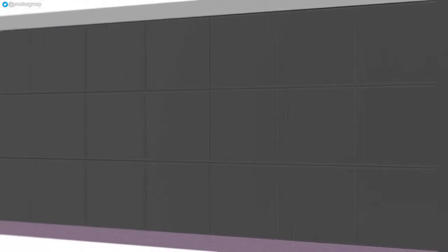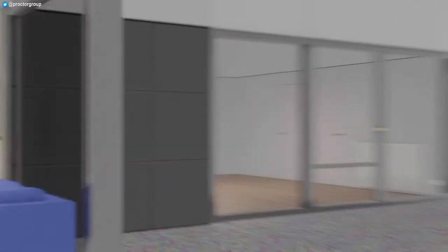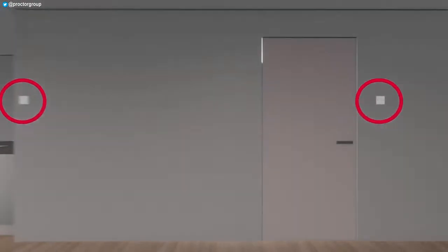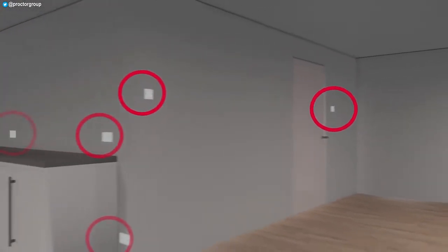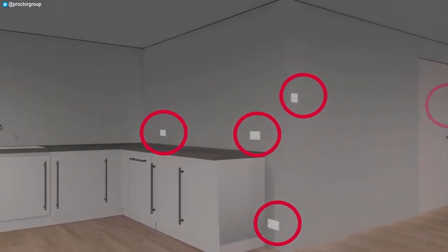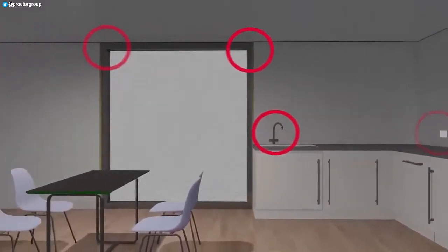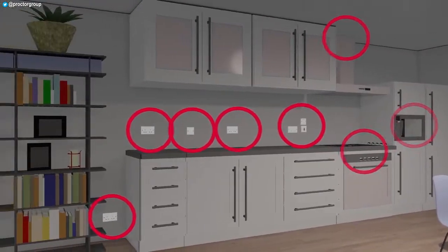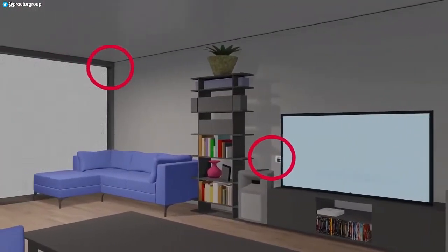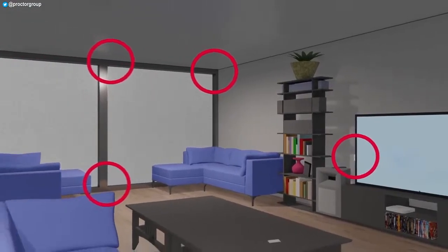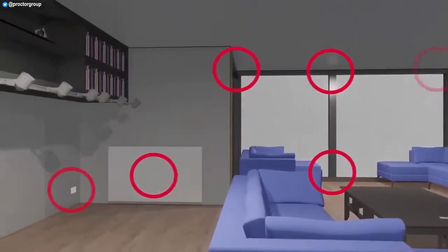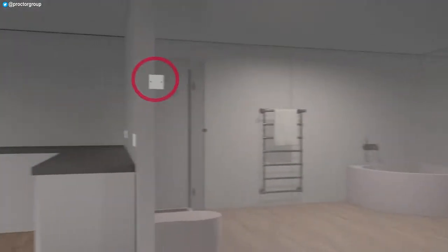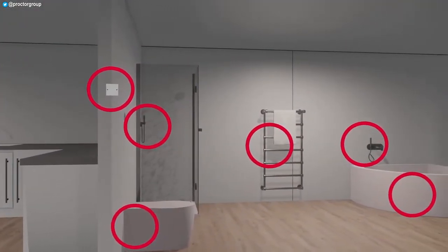As we can see here, if we keep the air barrier internal, that means a lot of tape and mastic required to seal all the switches, sockets, pipework and other services that modern buildings require. A lot of the sealing can be done off-site, but it still takes a lot of time to do correctly and further care is required to ensure the seals are not broken or damaged during transportation and assembly. Even small punctures, broken or misaligned seals or loose tape can significantly increase the air leakage rate when tested, leading to expensive and difficult remediation measures to meet regulation requirements.